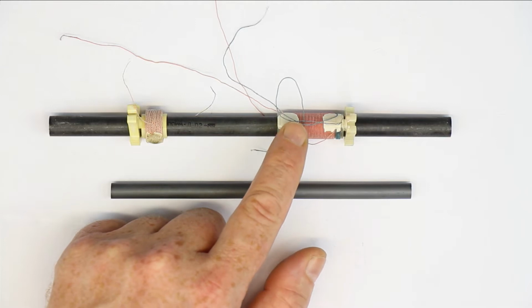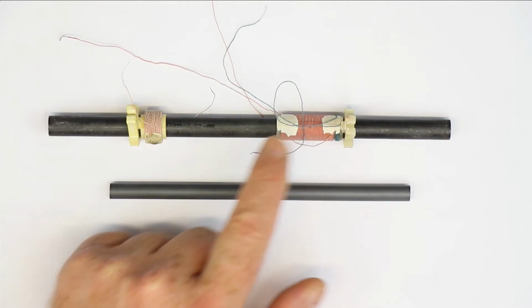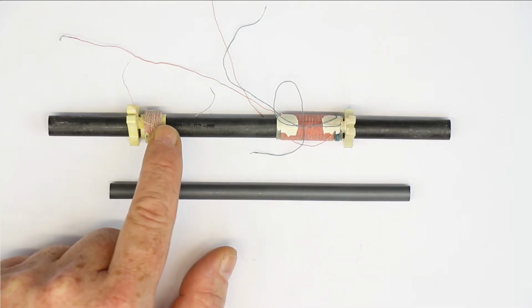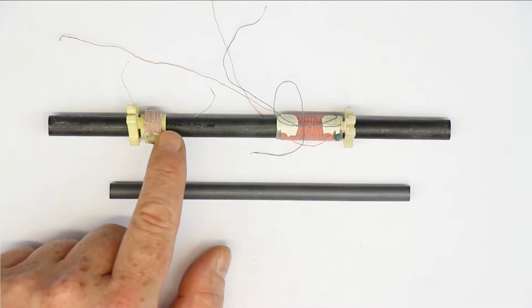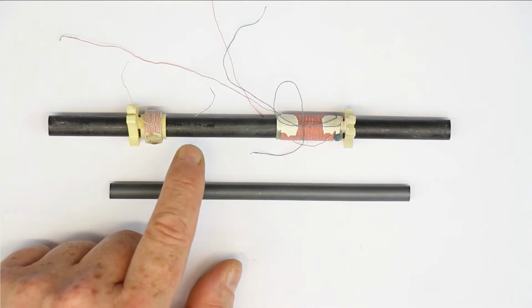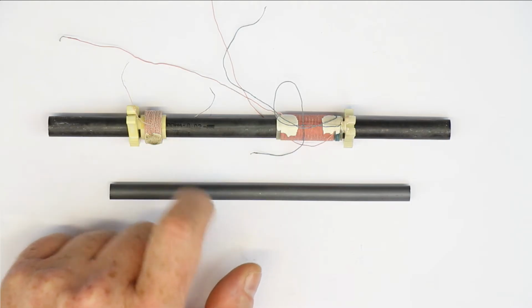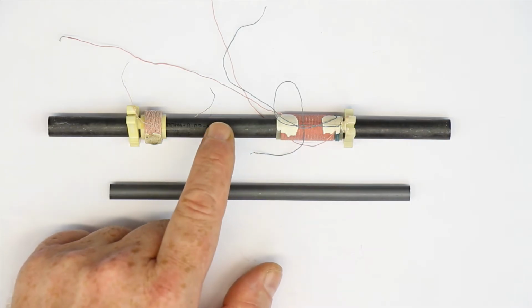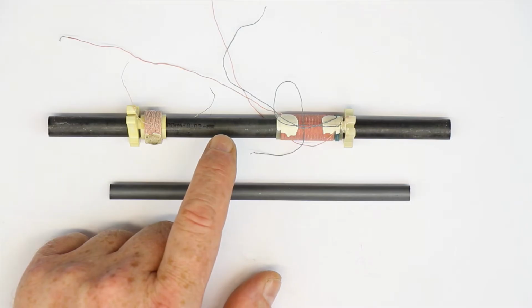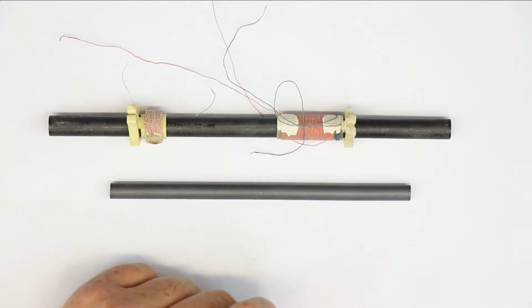Standard is 170 microhenry for the medium wave range and 2.2 millihenries for the long wave range. When you couple these inductances with a 500 picofarad capacitor, then you get the right tuning range for the frequencies of the medium and long wave range.